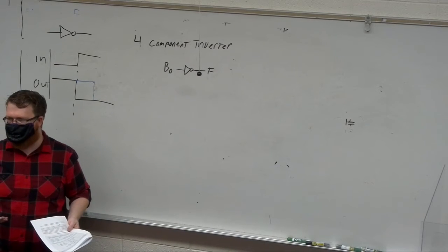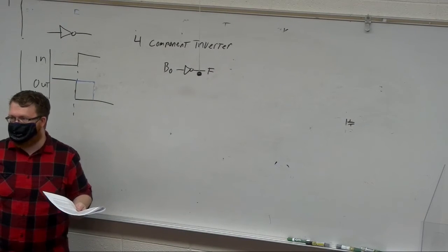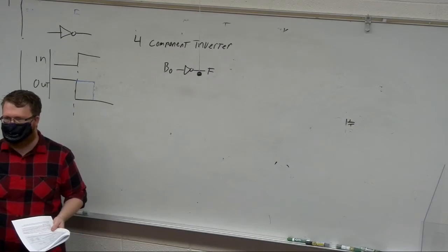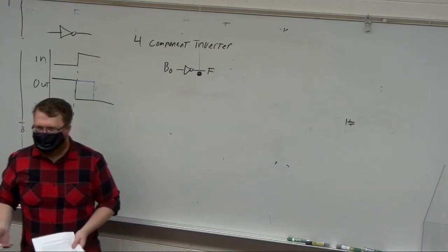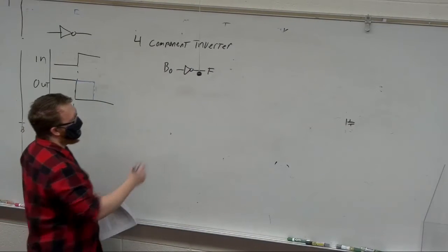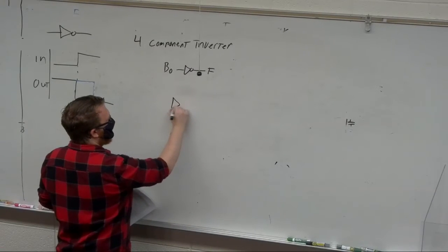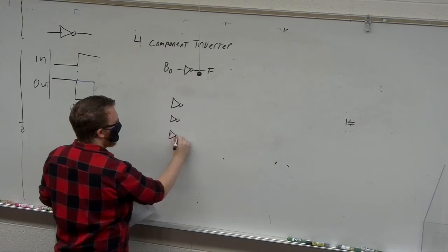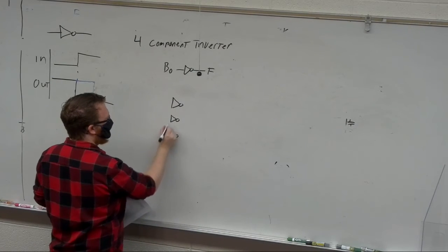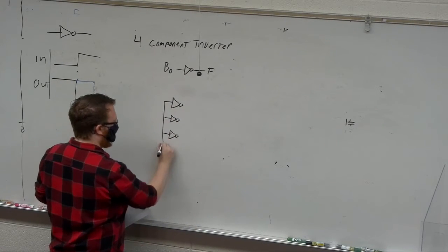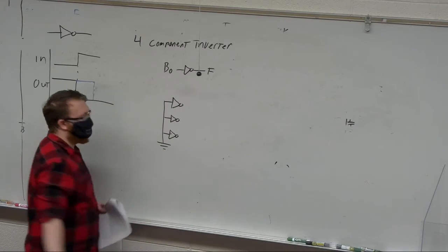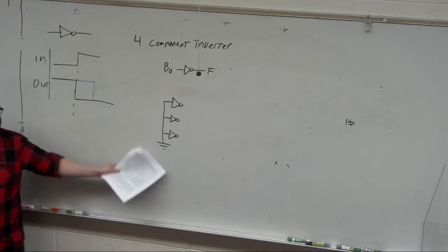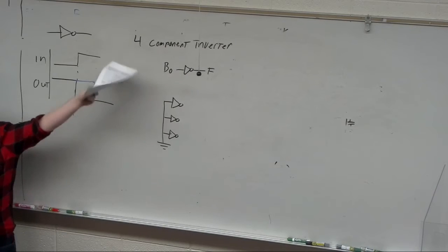Do I just want to leave the inputs hanging? That's what we've done before in the labs, right? Well, in the real circuit, you probably want to do something like this. Just ground the inputs. Or you could raise it up to power.